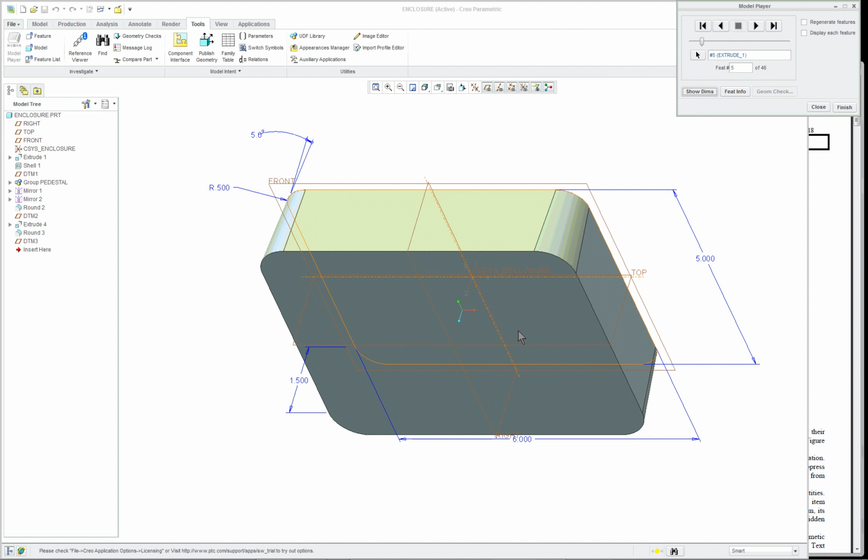And you have your first extrusion, first solid feature. Now in this case we use the capability where we put the taper into the first extrusion instead of adding a draft. You put a taper on, then you can't use draft. So you can't put a draft on top of a draft, you can't put a round on top of a round. So just understand, if you put a taper on here, this is what you're going to be using for your draft.